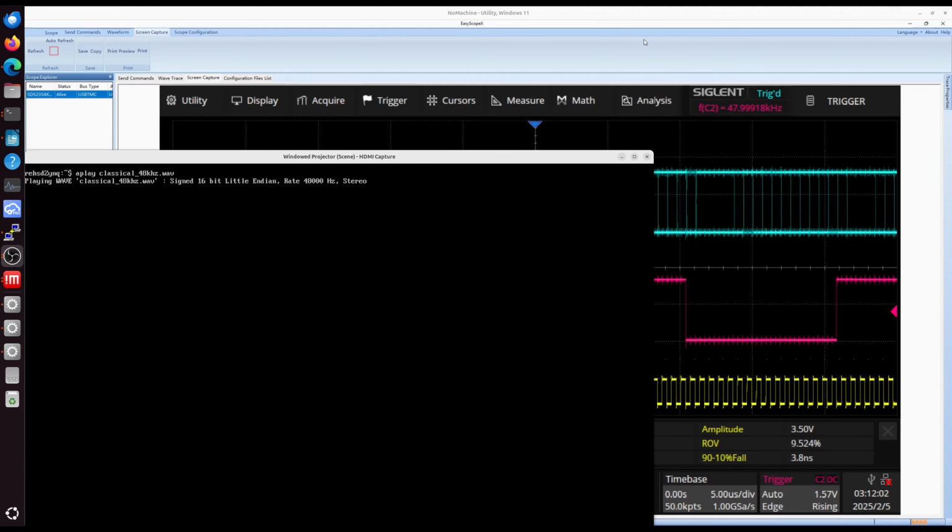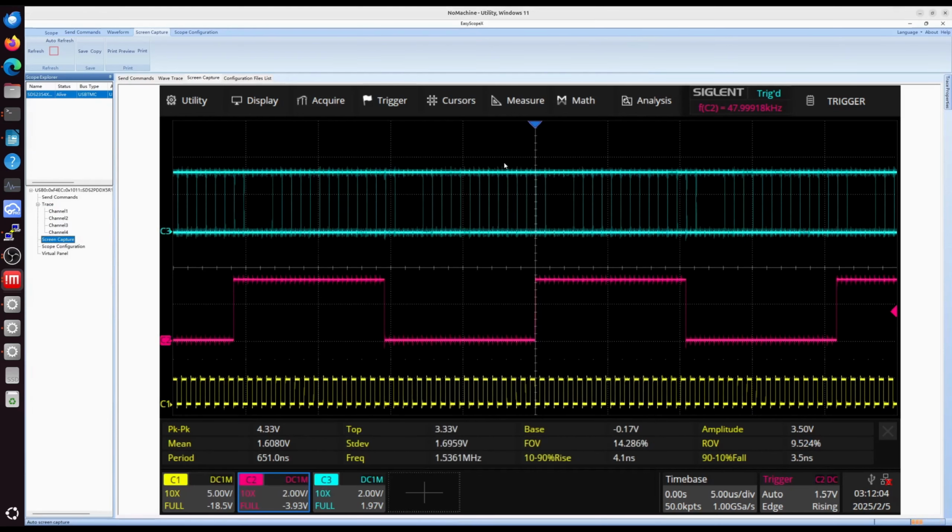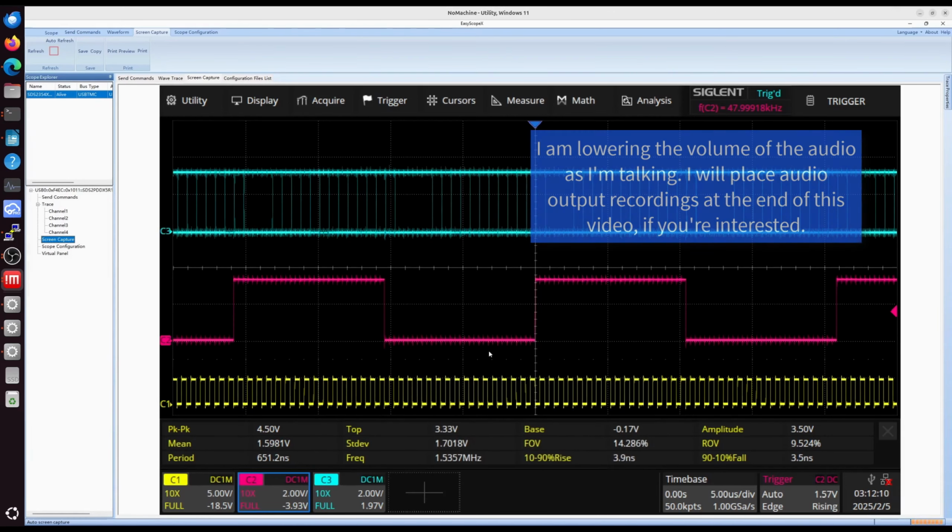But if I pull this up while that's playing, this is my scope. Ignore the little spikes, the overs and unders. It's just because I've got long wires and not good connections to grounds, things like that. It's just a bad connection from my scope to my board. But it's enough for me to at least see what's going on as far as frequencies and such.